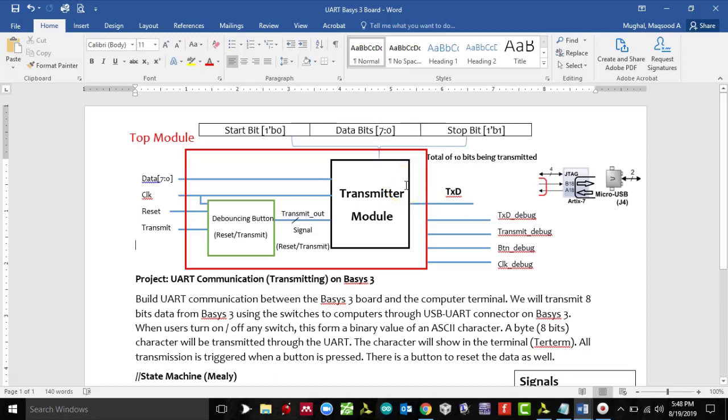So a bit we're gonna be using, and I'll show when we do the coding, we can get it to work through a shift right register. Whenever the data comes in, it will actually start shifting 1 bit by 1 bit serially, and then at the output it's going to convert the data back into parallel. We are also going to add a start bit and stop bit. So for the UART, it would be clear when to start shifting the data, or when the data is coming, and when all the data bits have been transmitted.